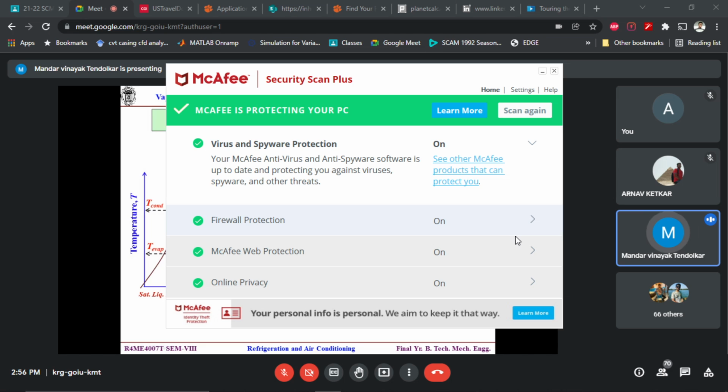Now more concerned toward this. What is this? Let's see. Okay, so we define for the cycle efficiency. This is the only definition in thermodynamics as far as refrigeration is concerned. The efficiency is a function of COP, so the COP of the VCC divided by COP of the Carnot cycle. The COP of VCC you have just expressed in terms of the Carnot cycle.